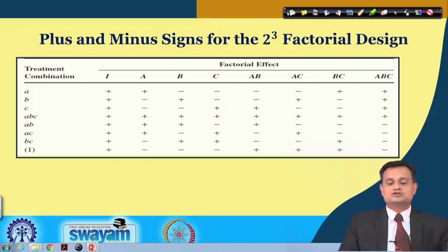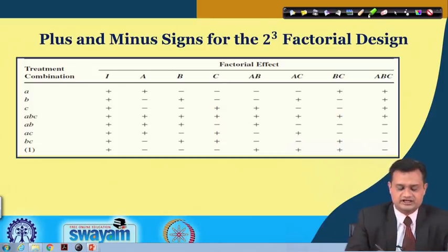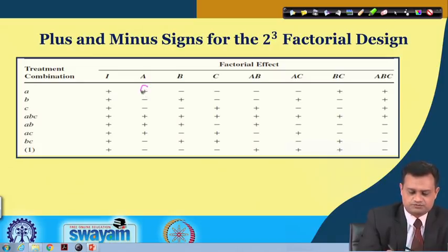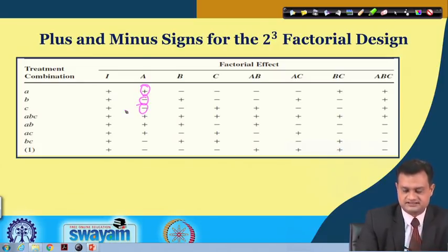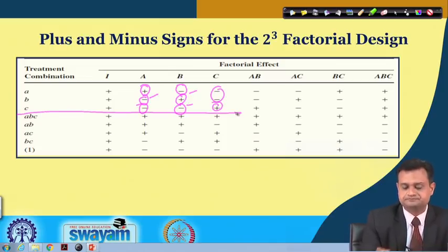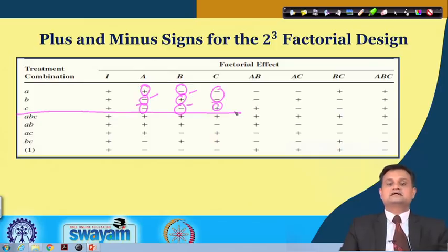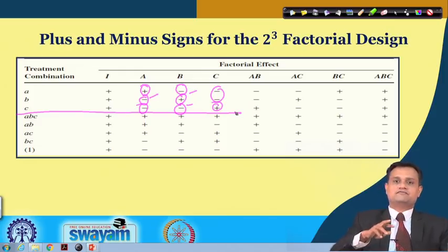and this kind of approach would not be good. So let us say once again, if I see A is changed first plus and then it is kept minus and minus. Now you see there is only one time change. If you see this is set minus, then again change and again change, 2 times change. This is only one time change if I just refer up to here. So you can say that the factor which is most difficult to change should be changed less, and hence you do not frequently change from low to high and high to low.